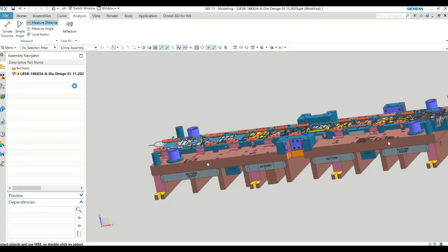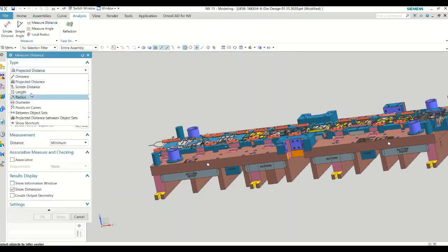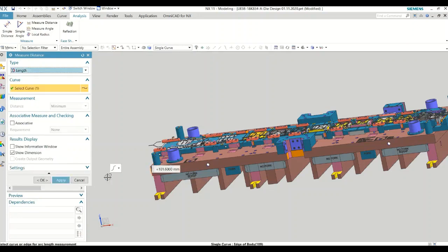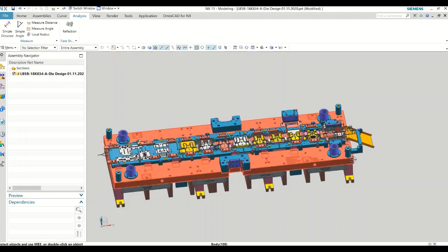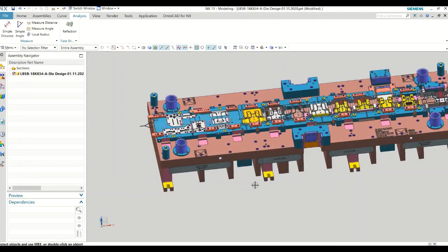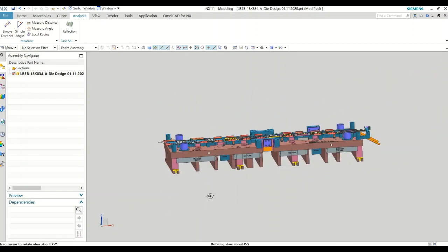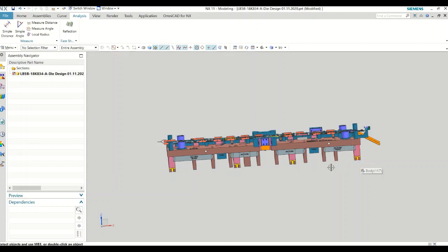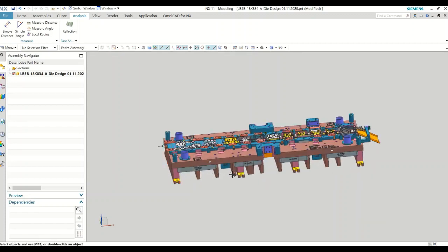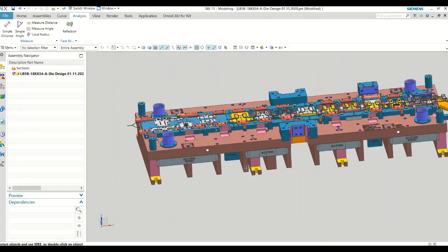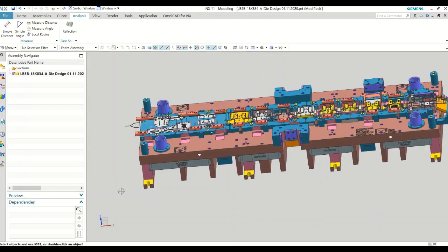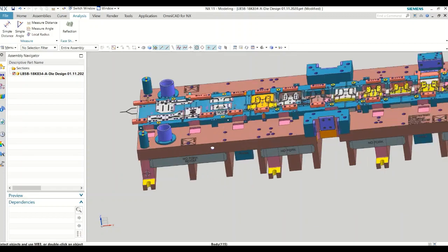Let me check that. Yes, it's 4 inches. So that's what we have taken, and for the rest of the gap we used parallels. It saved our material, machining, everything. So that's the standard. We have this parallel. Wherever we have a clamping slot, that's a clamping parallel, and otherwise a normal parallel. All of them are lower parallels.